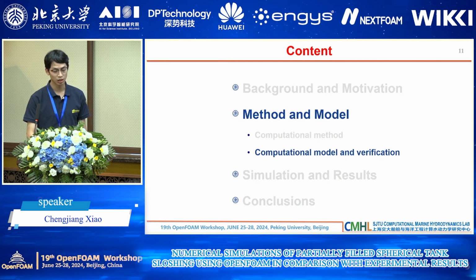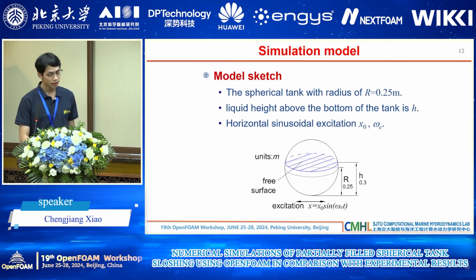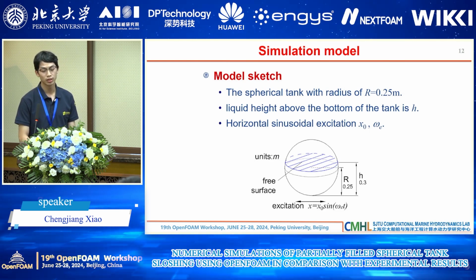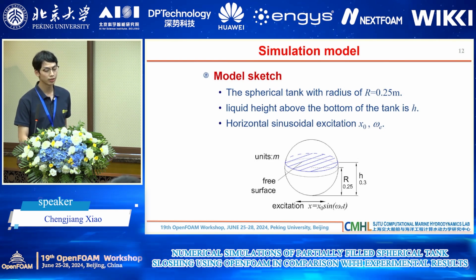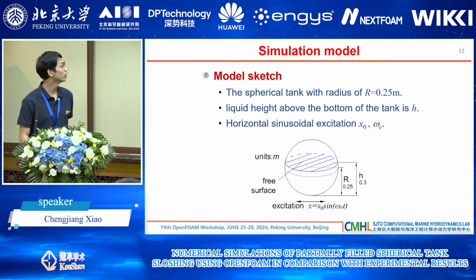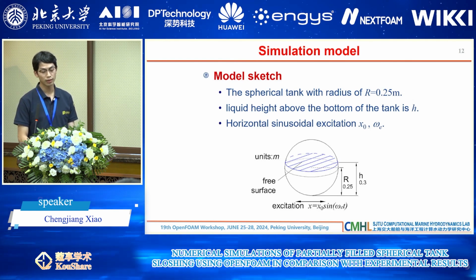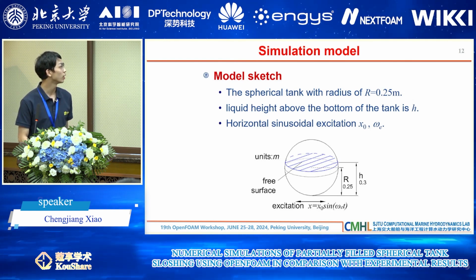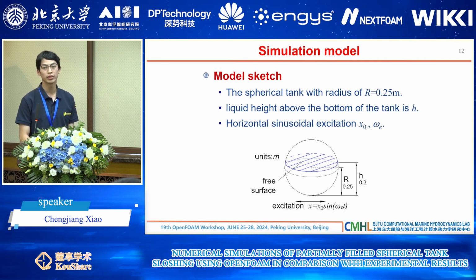Now let me show the computational setup and the verification. Here is a sketch showing basic parameters of the simulation. The h is the height of the free surface from the bottom of the spherical tank. The excitation is in the direction of the x-axis, and x0 and omega_e are the excitation amplitude and the circular frequency respectively.